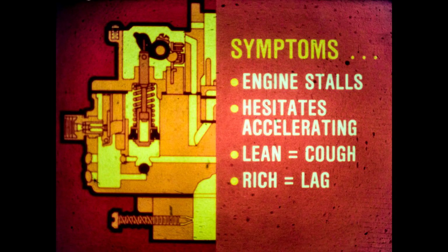Accelerator pump service may be necessary if the engine stalls when it's hot or cold, or if it hesitates accelerating at low speeds. A good tip to remember is that if the engine coughs through the carburetor and the air horn looks sooty, the mixture is too lean. An over-rich mixture could cause the engine to lag or hesitate, but it won't cough.